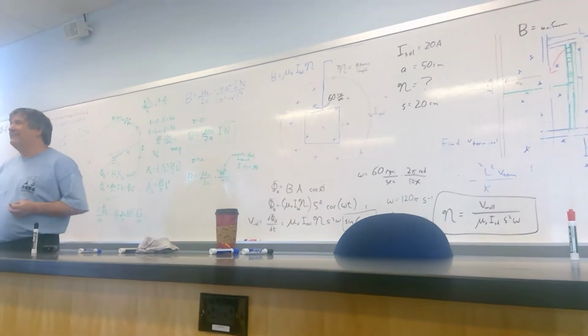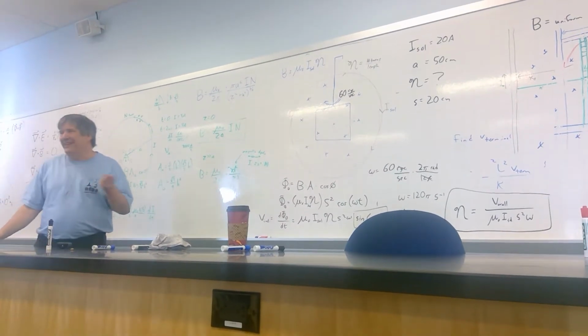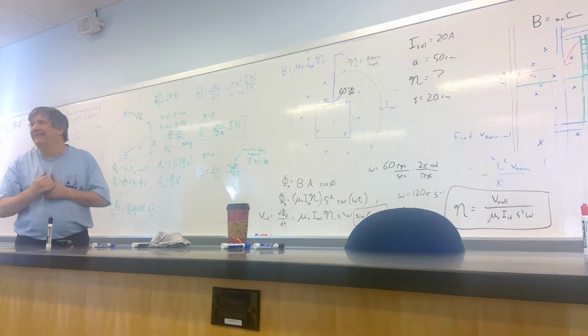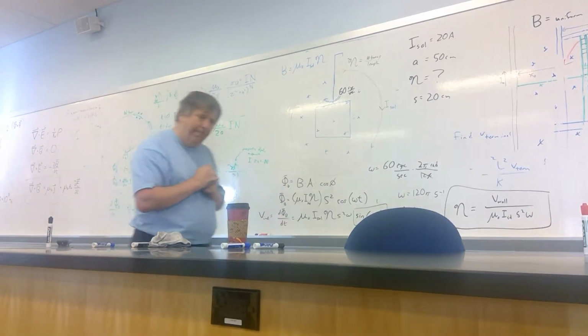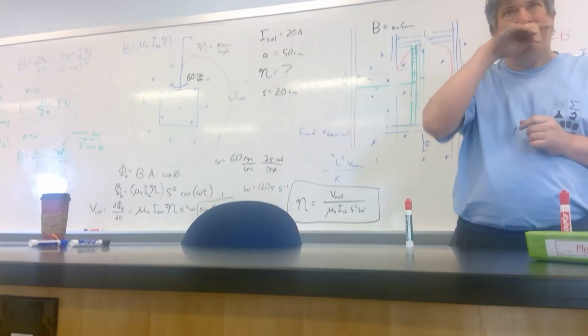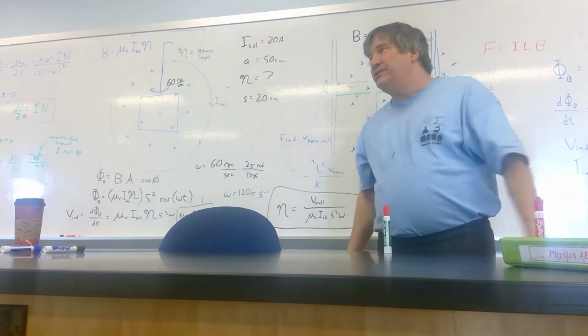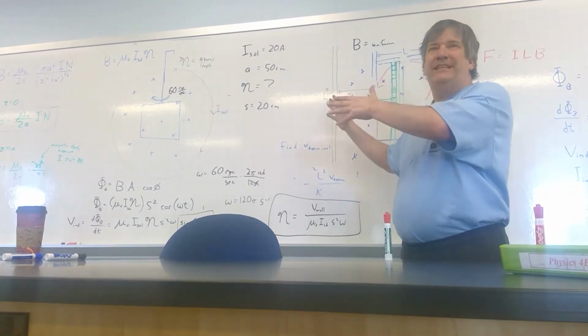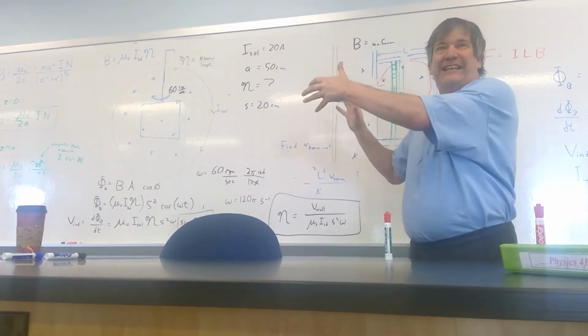And yes, that could be the kind of thing that I would ask on part B of the question: how would you improve this design? So yeah. If you were actually generating power with this, you wouldn't use a solenoid because a solenoid takes power to run in and of itself, right? This is true unless my whole thing was, no, I've got available a really powerful DC source, but I need AC power here.